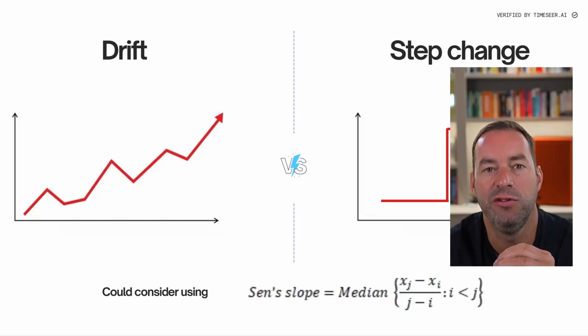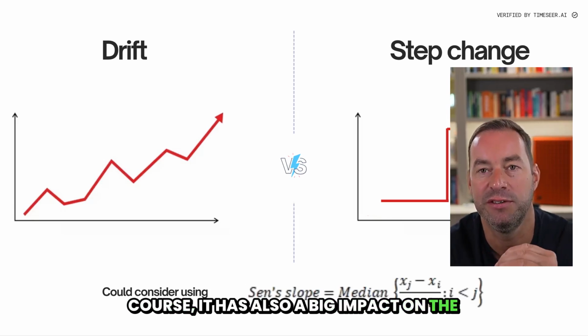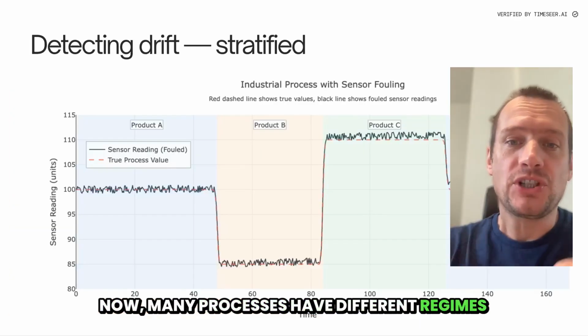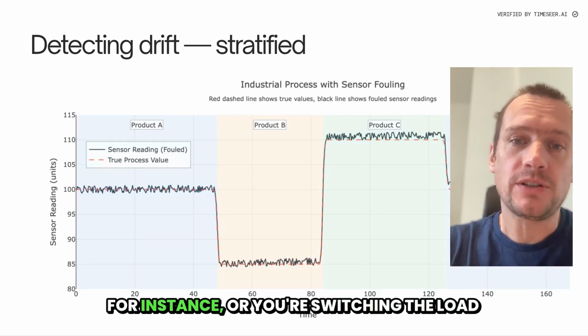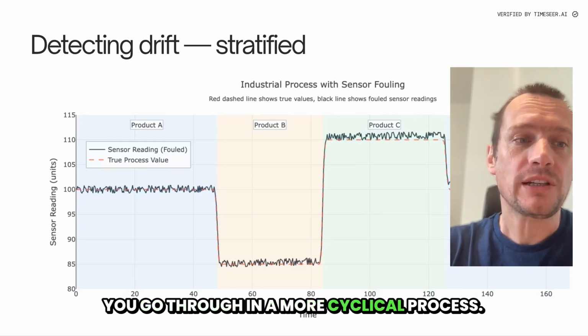And if you do step changes in your process, of course, it has also a big impact then on the drift detection. Well, we'll come to that. So many processes, or maybe we can talk about it now. Many processes have different regimes and alternate between those regimes. Say you're producing different products, for instance, or you're switching the load of a factory, or you have different phases you go through in a more cyclical process.